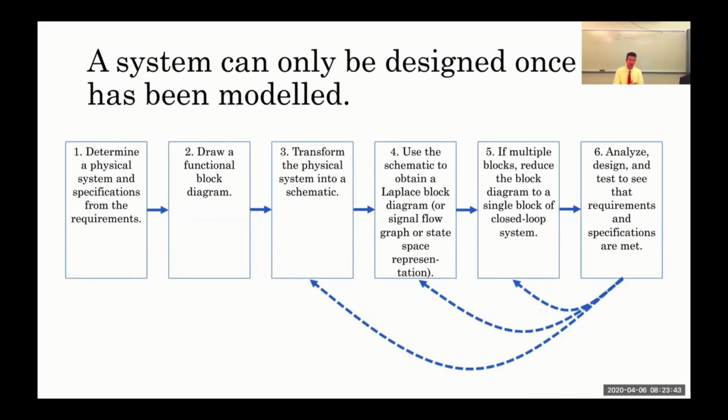So then you would use that schematic, circuit diagram if you like, and transform that into a block diagram. What are all the small components and how do they all talk to each other? What is the differential equation that relates inputs to outputs? Once you have that differential equation, then you can start talking about the Laplace transfer functions of the different components of the schematic.